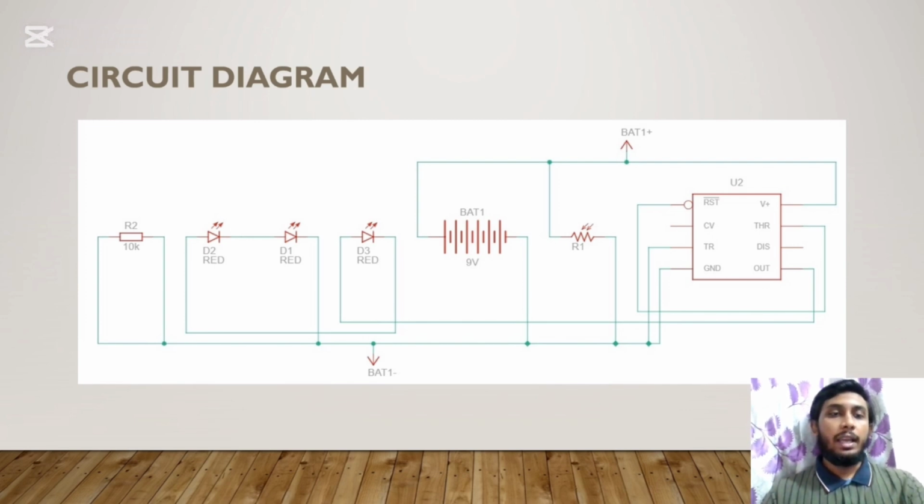The explanation is that an LDR works by allowing more current to flow through it when exposed to light, which translates to a lower resistance. In darkness, its resistance is high and little current can pass through. So when there is a lot of light, the LDR has low resistance, which means the voltage divider gives a low output voltage. The low output voltage turns off the transistor, which cuts off the current to the LED.